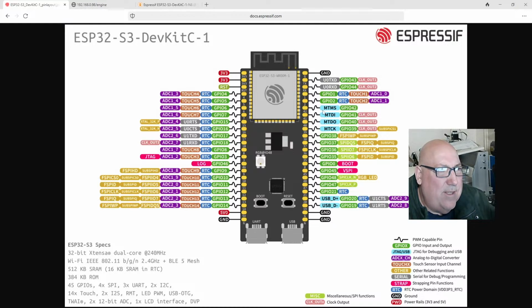But then I've got some pins it doesn't know about. Let's set it to an output GPIO. 45 GPIO. So let's just change some of these numbers to something else. Something that we're not using. 36 and 35. If I remember right, some of them are input only or output only.